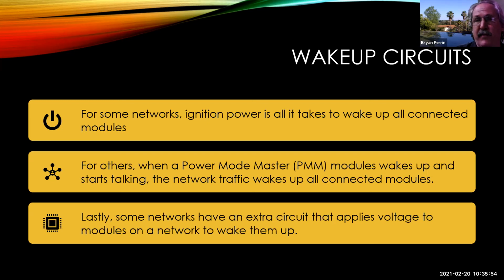Yeah. Right? If I know, hey, the computer set a code because on this wire, when it turned this on, the voltage was over 5 volts for more than 15 seconds. Bingo. Now I know what I'm looking for. I'm not looking for a spike. I'm not looking for something that happens for 200 milliseconds. Whatever happened under this situation happened for a long period of time, and this is when it happened. Let me go test for that.